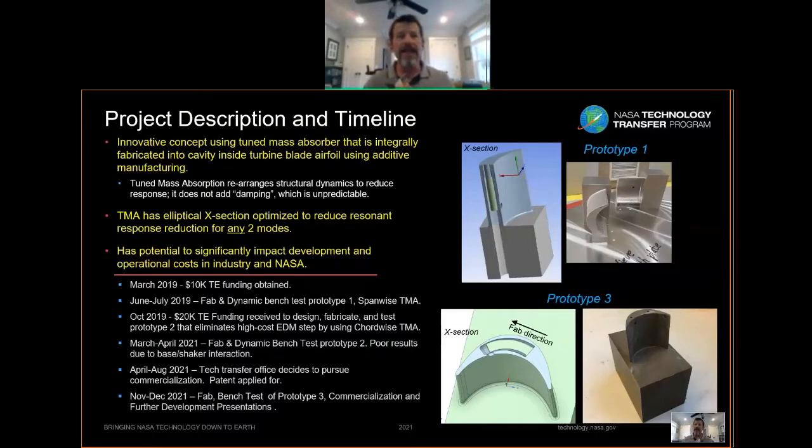If you're familiar with additive manufacturing, that's required whenever you have an angle of more than 45 degrees, because the material can't support itself during the additive manufacturing. So you have to build this scaffolding. With what you see, the scaffolding is quite easy to remove.